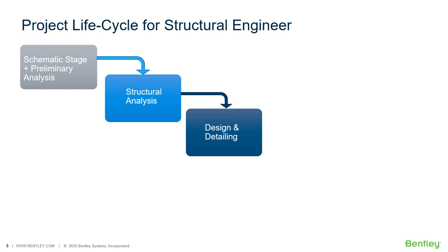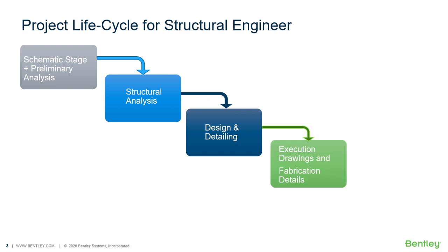Once that is done, then the second stage comes wherein the actual rebars are placed depending on the section. After that, generally engineers will follow through to create execution drawings which are shared at site. And at site, they will be further enhanced to go into fabrication drawings or what we call as bar bending schedules, which will be actually executed during the reinforcement placement. Simultaneously, structural engineers generally create reports for submission to authorities or peer review and also create reports for quantities which are very important from the costing perspective. So this is the total life cycle for a given project.